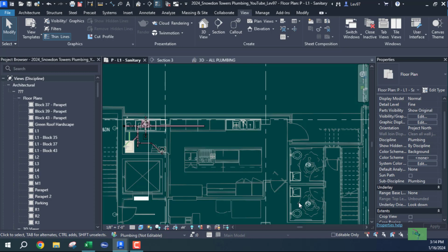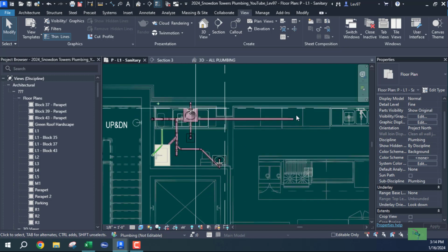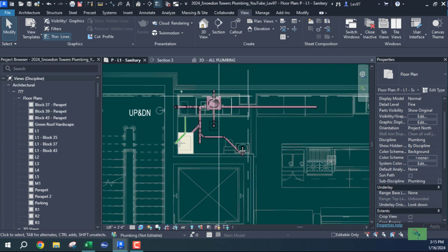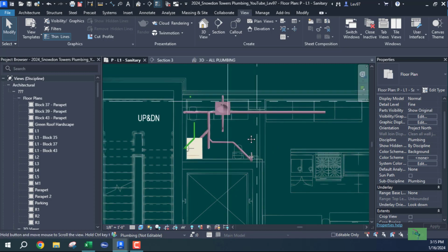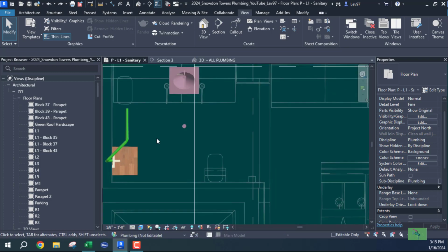I'm gonna collect vent from the other bathrooms, okay. So the vent is gonna come, the source is gonna go, this is the riser, and other vent load will come from the same as this waste pipe. So I have to have another vent that's going to be a 2-inch vent, coming from right to left, okay? So let's undo this, okay?